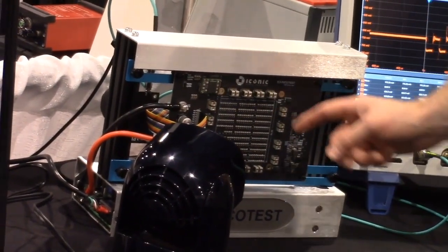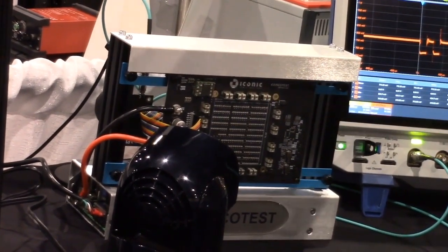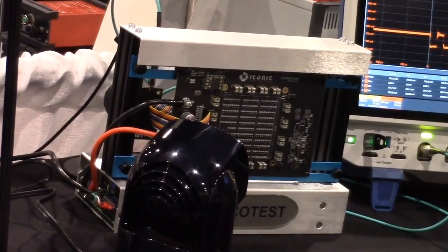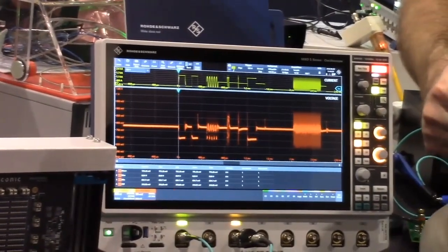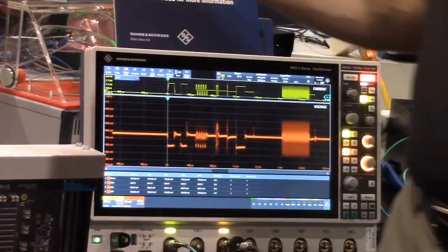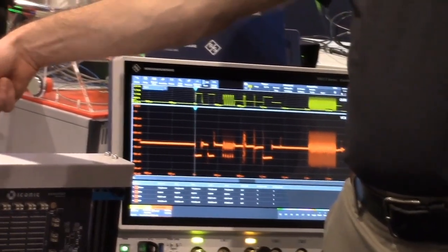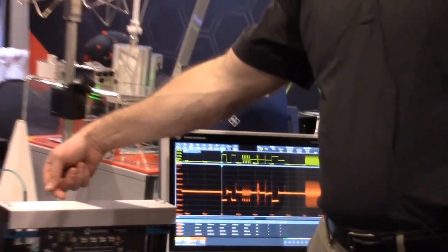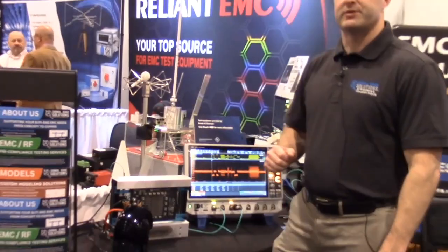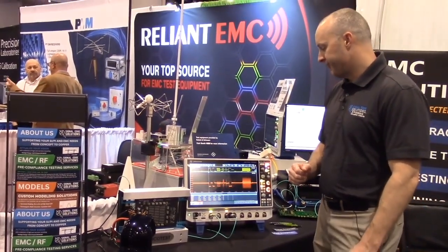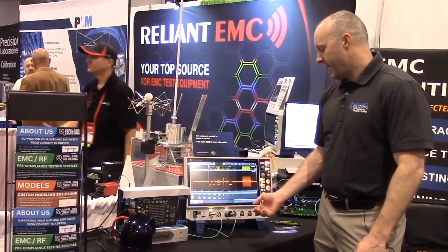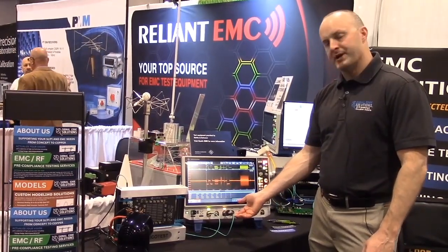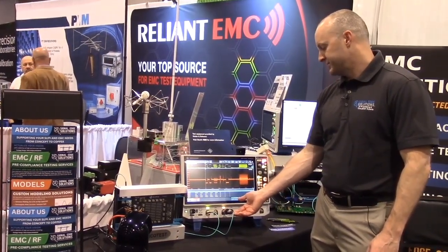There are 512 GaN FETs here, and that gives us a huge range of fidelity to do that 2000 amp step load solution. We have 11-bit control. We can do over 50 megasamples per second. What you can't see is we're measuring on the back side of this platform with another PicoTest probing solution, a P2104, and we have our emulated current coming into channel 1, and we have our voltage that we're measuring from the emulated current response coming into channel 3.